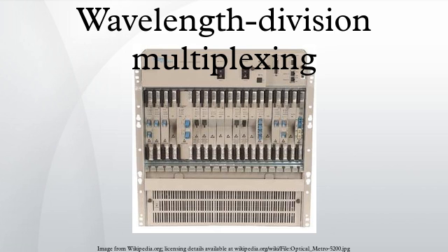Transceivers versus transponders. Transceivers: since communication over a single wavelength is one-way, and most practical communication systems require two-way communication, 2 wavelengths will be required. As a result, at each end both a transmitter and a receiver will be required. A combination of a transmitter and a receiver is called a transceiver. It converts an electrical signal to and from an optical signal. There are usually two transceiver types based on WDM technology.